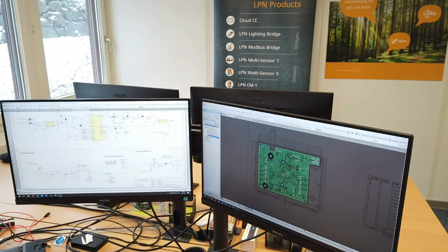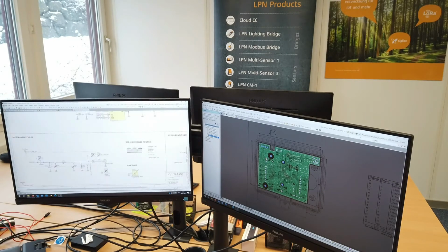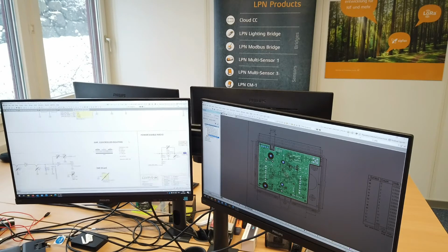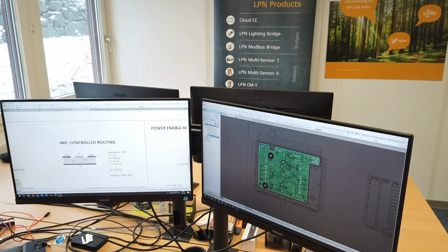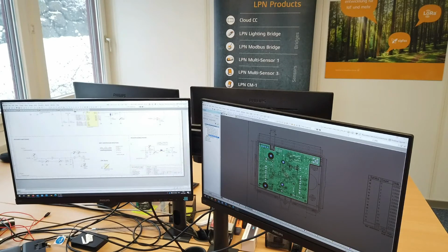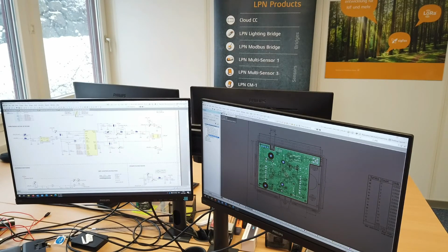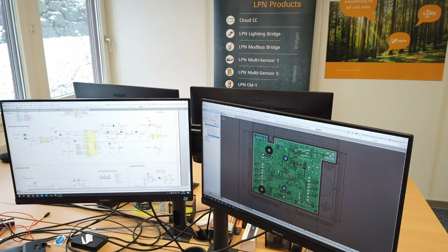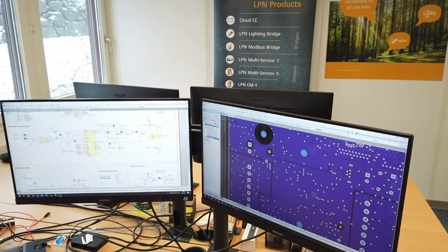The actual energy we can take out of the battery is at the end much smaller than the nominal energy we see on the datasheet. So this is really a critical point for us to know how long our system is actually going to work on that battery. Take special care when choosing the DC-DC converter, as it is not always important to have the highest efficiency, but in our case, as we're battery powered, we need to have the lowest quiescent current, as we're always sleeping.